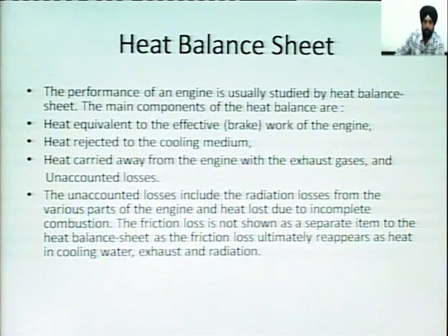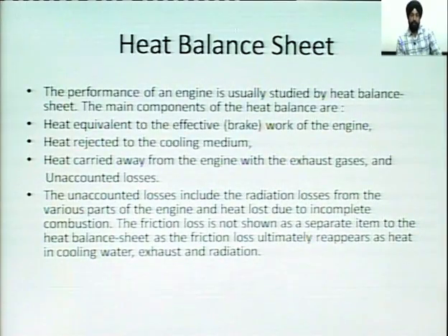So the heat balance sheet is simply a procedure to know what fraction of heat supplied is carried away by the cooling water, what fraction is carried away by the emission, and what percentage of it is converted into useful work. So the basic purpose of preparing a heat balance sheet is to know about the various fractions of heat we get from the total heat supplied.